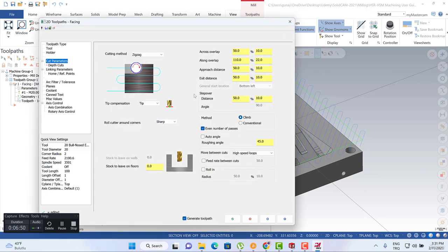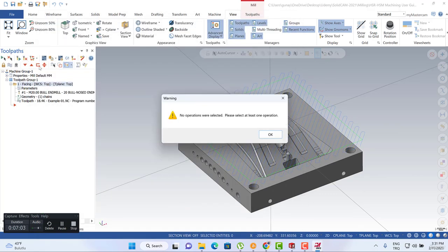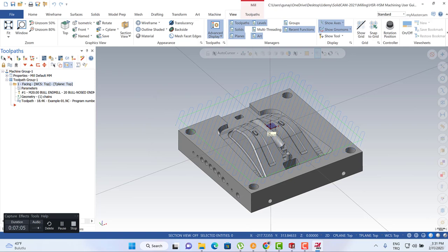When I turn to parameters, we can also make them according to my tool diameter. We can also select 40% of my tool diameter. It is 8 millimeter as a step over. Oops, that's calculated automatically.